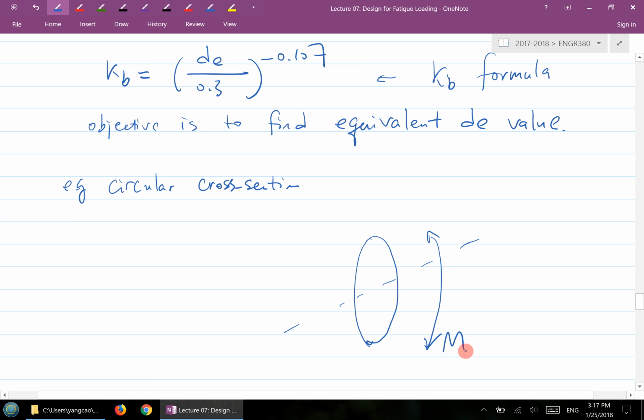So what we do is we look at specifically a region. Here I select 2 regions, and this is the so-called 95% of the maximum stress. Where's the maximum stress? It is here. When you move closer to the neutral axis, the stress will be smaller, so you're looking for the place that has 95% of that value. That's the region created over here.